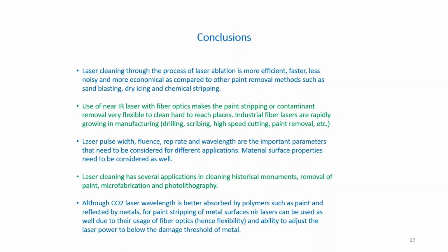And we went through the important parameters in the physics part of this presentation. So one has to be very careful about choosing the proper laser and the laser parameters. And basically, if you don't want to create much heat effect, better either use a UV laser or use a very short pulse width laser. Laser cleaning has several applications in cleaning historical monuments, removal of paint, microfabrication, photolithography, and then the